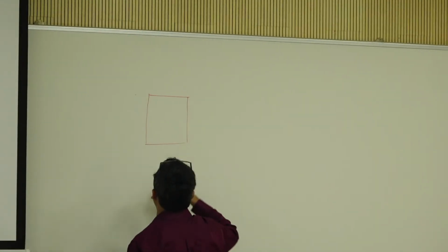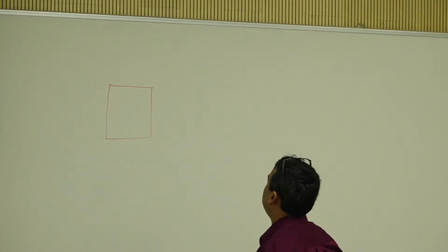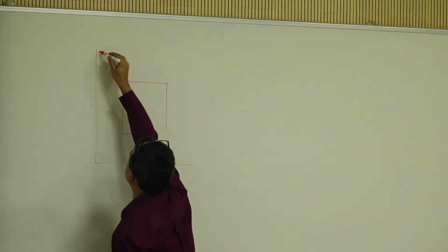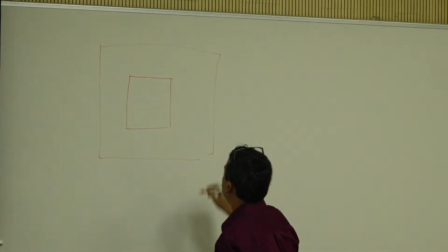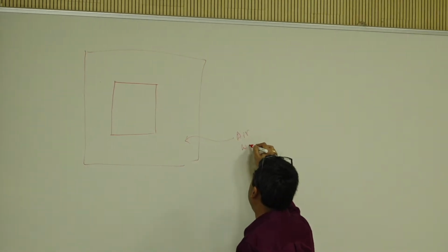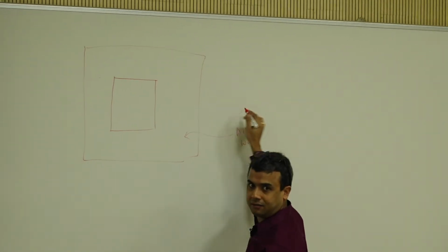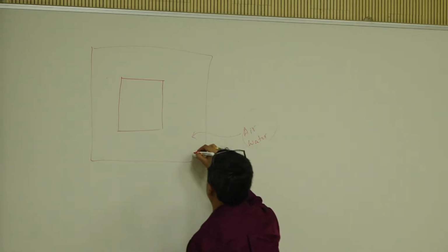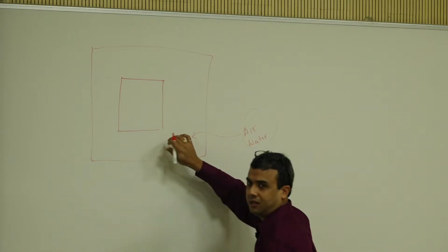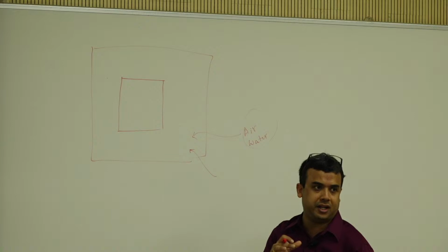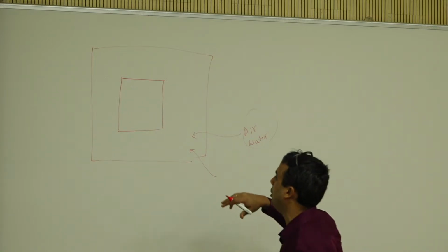So we're talking about cylindrical triaxial, and you know why it is a cylinder, we talked about it. So we have a chamber. Inside the chamber we have some kind of a confining fluid or water, right? You've used that. When you apply a confining pressure to this chamber, it's Pascal's law. It is normal in all directions. It is hydrostatic. It is equal in all directions.